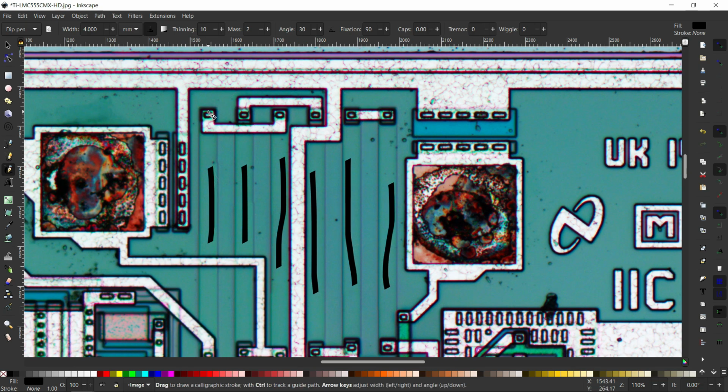See here the connection from each resistor, because here they have implemented an interdigitization based matching pattern. See here you can see this resistor and another resistor. I'll make a different color for better understanding. So the first resistor, this resistor, and then the other resistor. Let me take a different color. So this one and this one, yeah, these two resistors are connected in a different color. Because they have interdigitized this pattern, this resistor and another resistor are connected together. On top of that, one more resistor here, so this one and this one are connected with an interdigitization structure.